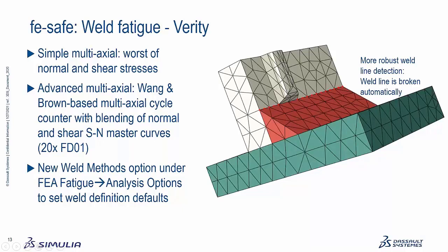But we also now have the advanced multi-axial one where we do a multi-axial cycle counting using the shear, the longitudinal shear and the normal stresses, and blending of the normal and shear master SN curves. Okay.